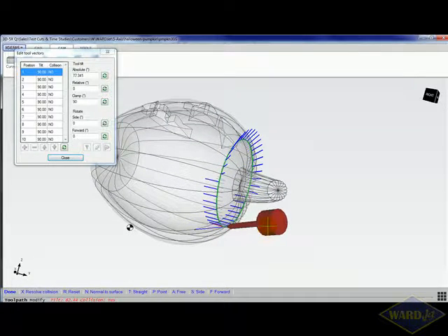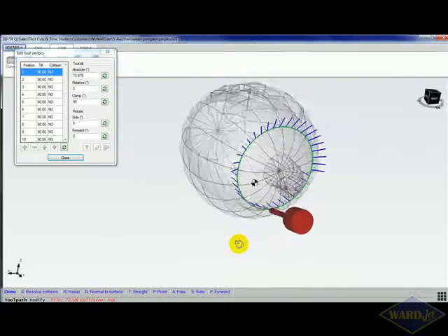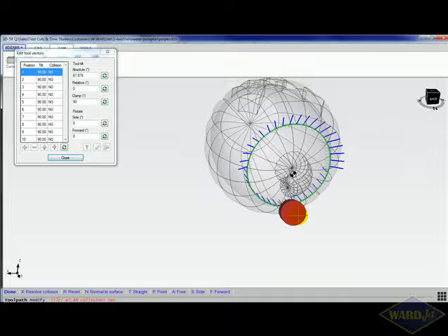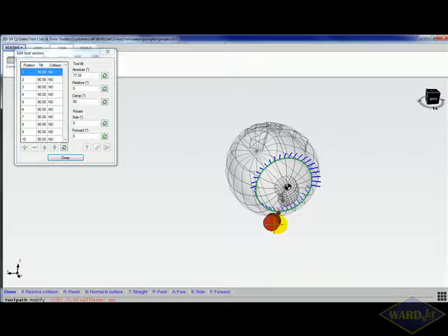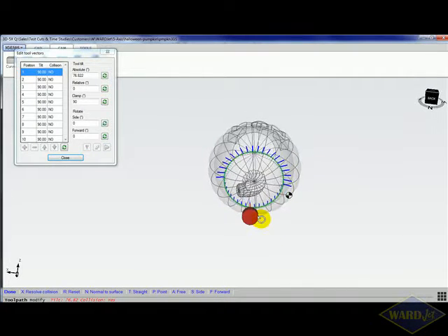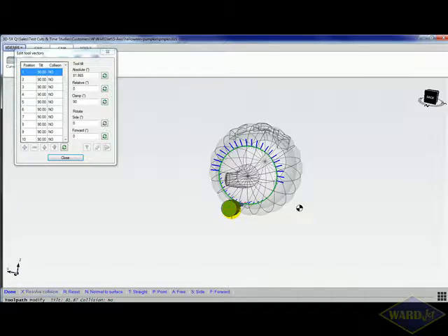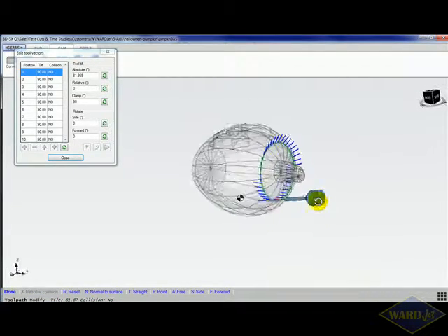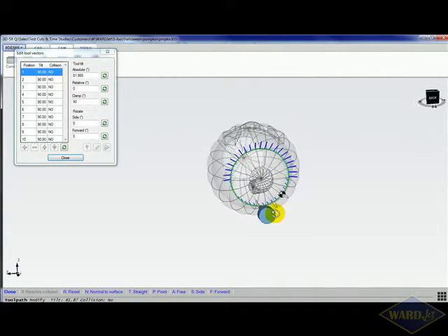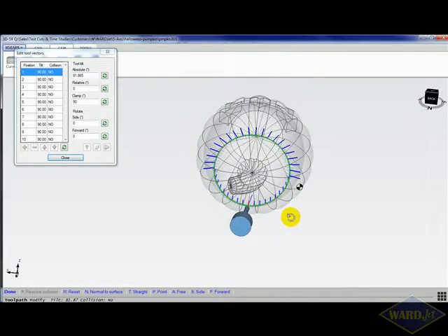And then when it's red, it means it's in a mode where it's either beyond the angle that the cutting head can go to or colliding with something. So if we go up, as I swing this around here, we'll go into a mode where it'll be blue here. And let's see, there we go. So that would be something where we shouldn't have any collision there.